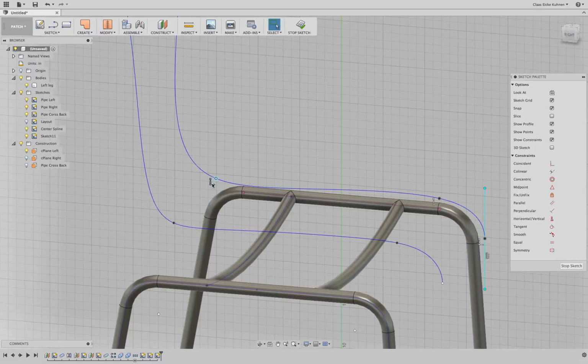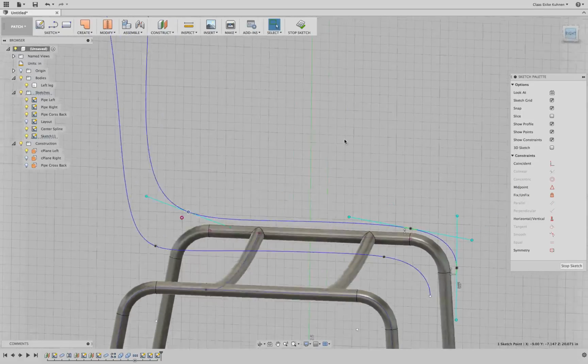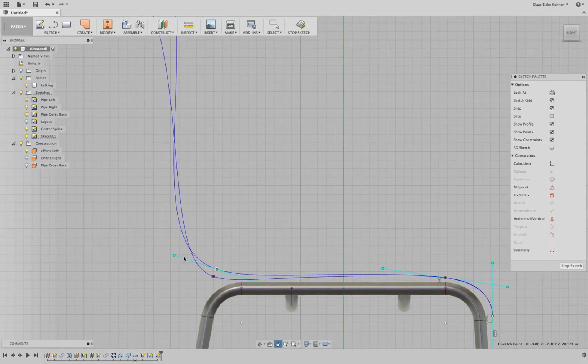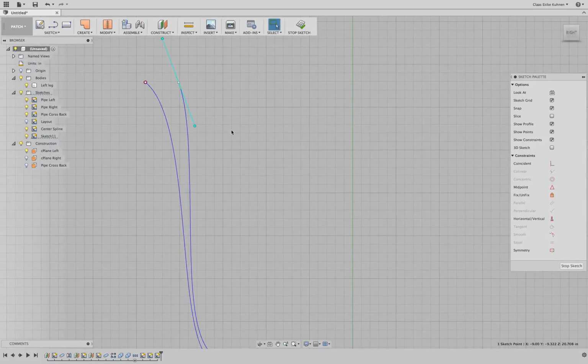There's actually a coincident constraint, because this fit point is snapped to this point from here, which I projected over, which is not what I want. So I will delete that coincident constraint. So I can move this one maybe a little bit more to there. And you will see why I will do that. And then maybe here we adjust this a tick more.